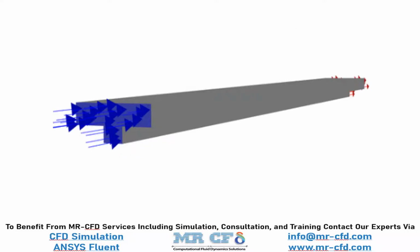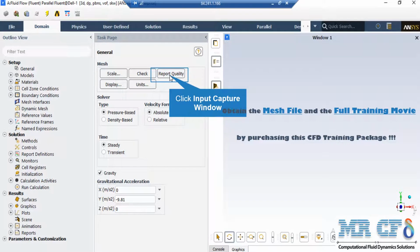The geometry of the present model is designed in ANSYS DesignModeler software. Also, by clicking on Report Quality, again in the Console tab, the Fluent software will give you the quality report for your mesh. For example, you can see the maximum aspect ratio of your mesh, maximum orthogonal quality, and so on.